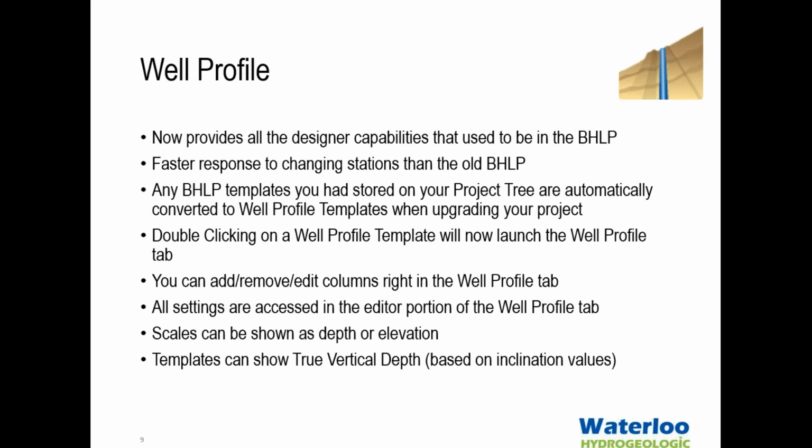Additionally, the templates can now be set to show true vertical depth. So if you do have deviated or angled boreholes, it can calculate the true vertical depth of your borehole data based on the inclination values that you have stored in the drilling protocol table. So let's take a look.